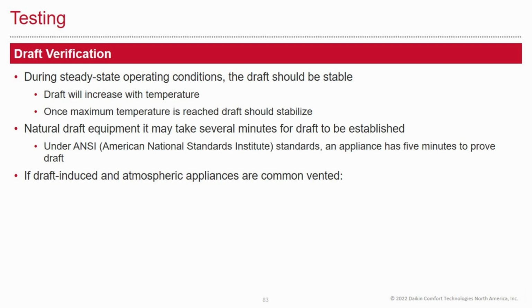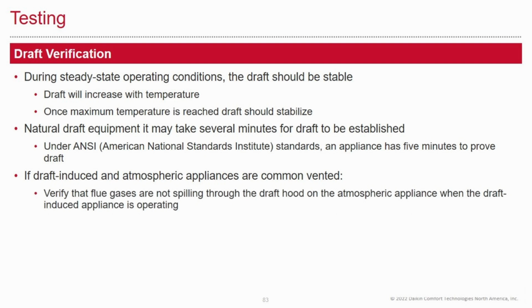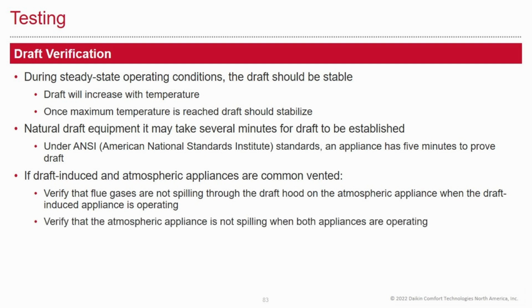If draft-induced and atmospheric appliances are common vented, verify that the flue gases are not spilling out of the draft hood on the natural draft furnace when the draft-induced furnace is operating. Verify that the natural draft furnace is not spilling flue gas when both furnaces are running.